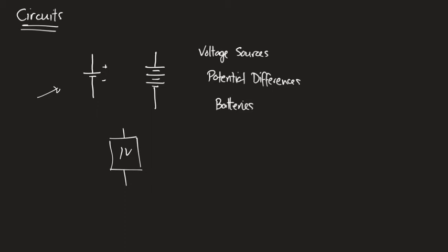We won't use them in the lab because they're inconsistent and they'll run out pretty quick. So we tend to use dry cells. But generally, I don't think you need to have the history of batteries here. A battery provides a potential difference. And so when we use batteries as a symbol here, we're using that as our potential difference in our circuit. It's appropriate that you understand that the positive side and negative side of the battery are fixed, and they don't necessarily determine the direction of current, but they do determine the direction of an increase in potential. So this direction on this symbol is an increase in potential.